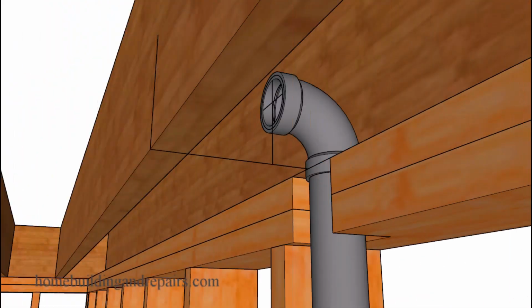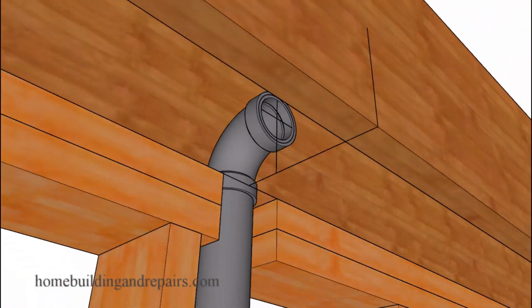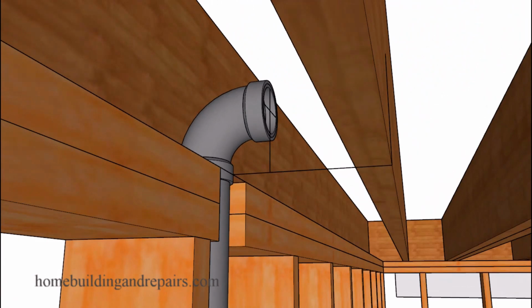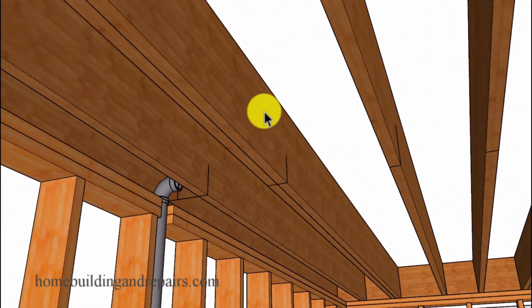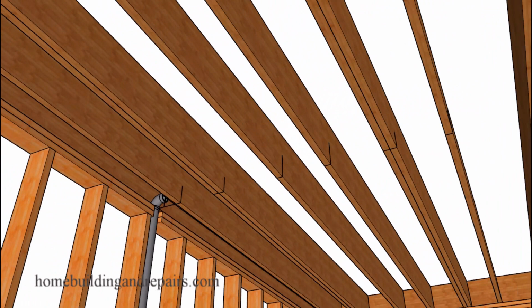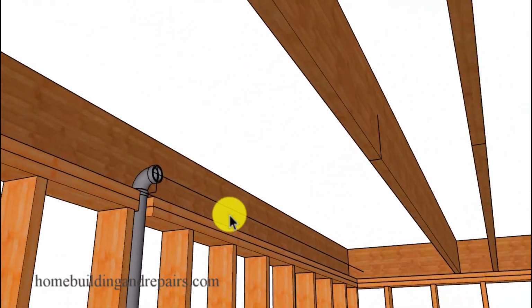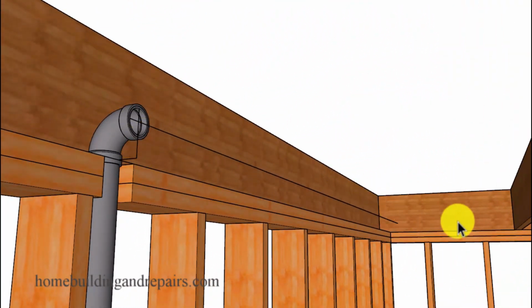And hopefully by now you're starting to wrap your mind around what's going on, and I can go ahead and show you how a plumber might do it. And that would be to get the location of this measurement here and this measurement here, the measurement from the bottom of the joist to the center of the pipe fitting, and then transfer that measurement to a piece of lumber. And in this example here, I'm going to transfer that measurement to the rim joist in hopes of making more sense out of what I'm trying to explain.